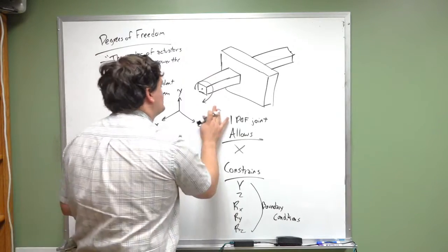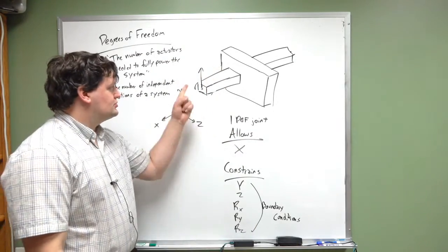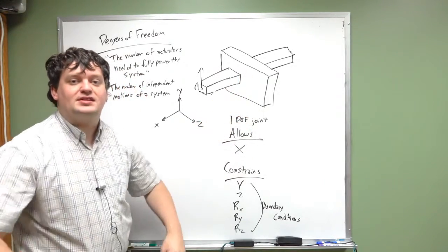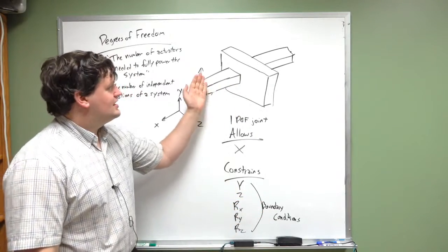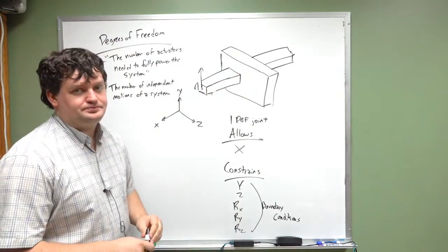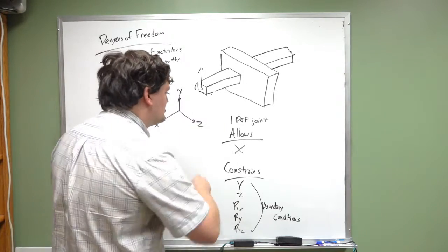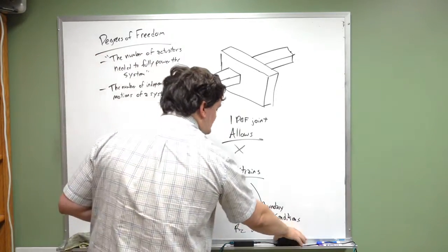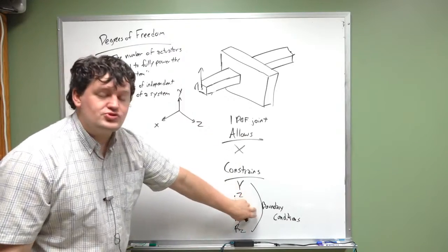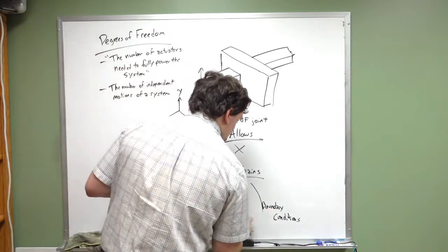Okay, so here, if I were to, on this component, have a vertical Y-facing force, just grab onto one end and lift upward, this will resist that movement, because it has a joint. The joint exerts a boundary condition that prevents this block from moving upward, because if this block moves upward, it travels through the other component. So it's a very interesting 1 degree of freedom joint, very simple, but the concept is understanding the degrees of freedom allows us to understand what the loading conditions are, what the boundary forces are for each linkage.